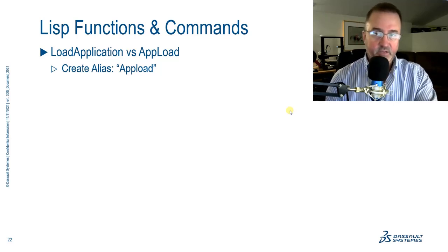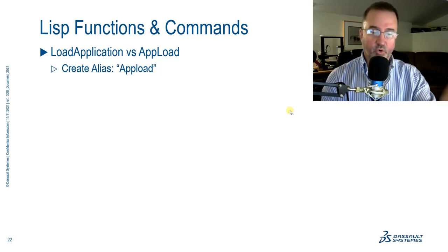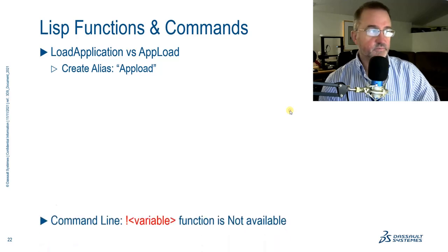Appload is not a command inside of DraftSight. The actual command is called load application. So if you're used to typing appload, or you have scripts that are typing appload to launch the interface, you just have to create an alias so that you have that command available.